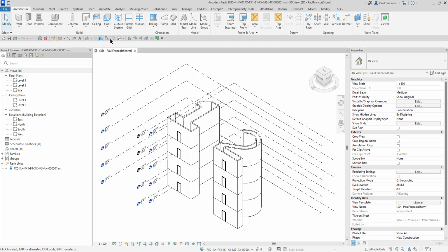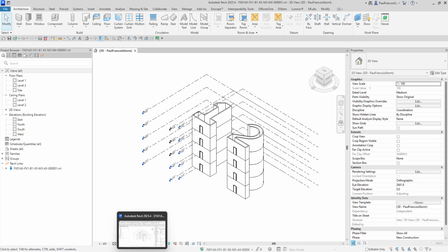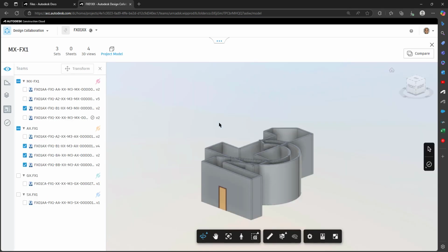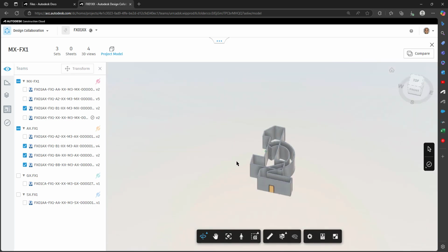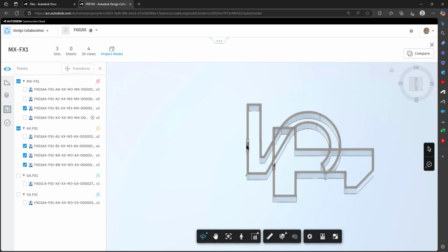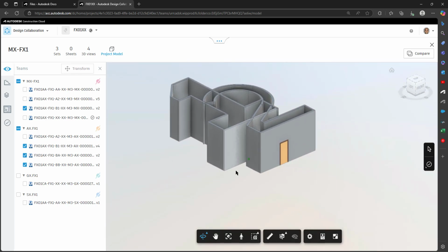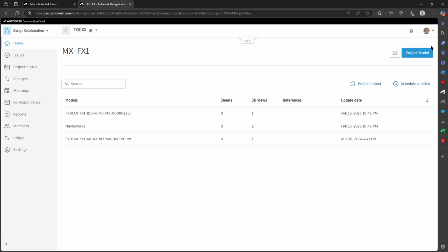So of course, if this is my mechanical model, if I had to visualize this mechanical model as a federated model within the cloud, I would expect to see what I need to see there. But as we saw, even though those second tier and first tier links are switched on, they're not appearing in the correct place. So the platform isn't built around this two-tier nested linking, which could make it interesting to work with. So my recommendation originally stands that you can either use groups or you can work at risk, which again, that's on you, but I wouldn't recommend.